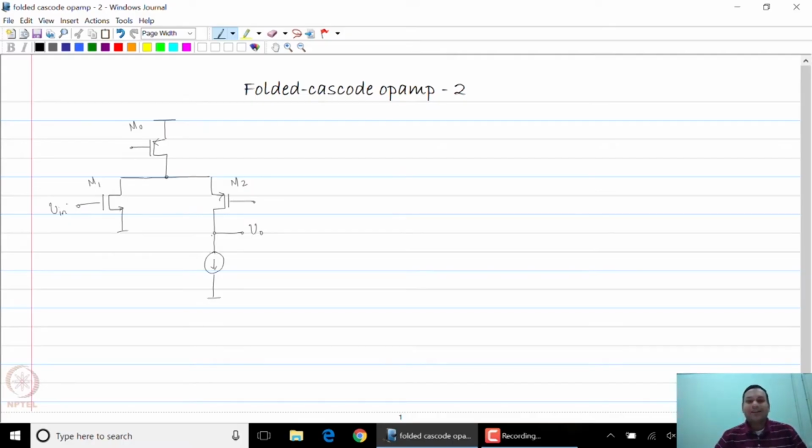Now how do you make a current source? You of course cannot make ideal current sources in practice. So the first thing you try to do is to replace that with a transistor. So please note that the output impedance of this, so maybe I'll call that R up, is something we need to write down, because this is going to become significant in a few minutes. So what is the expression for R up?